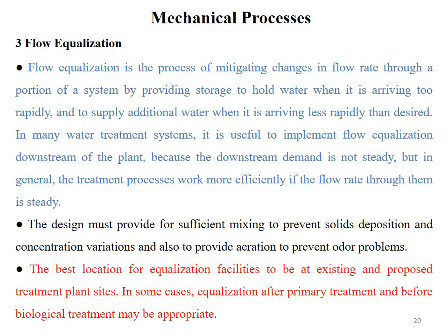And the design must provide for sufficient mixing. Design of these flow equalizers must provide for sufficient mixing to prevent solids deposition and concentration variations, and also to provide aeration to prevent odor problems.